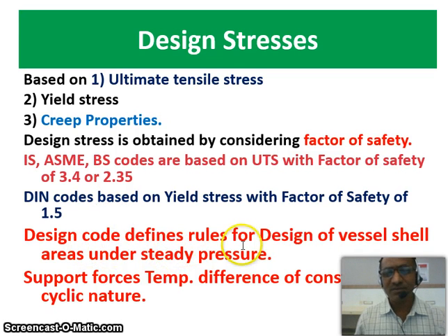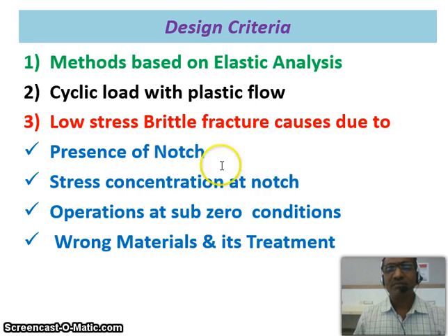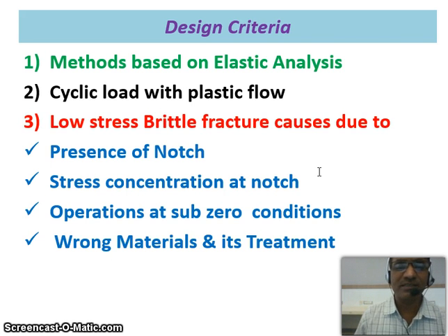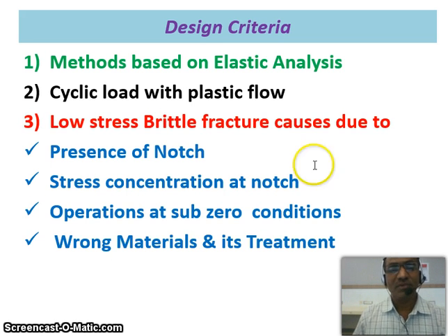These design codes define rules for design of the vessel shell areas under the steady pressure. Support forces in that case, and also the temperature difference of the content are cyclic in nature. There are various design criteria which are being used for designing the pressure vessel. They are based on elastic analysis, based on cyclic load, or which is subjected to the plastic flow of material, or low stress brittle fracture.